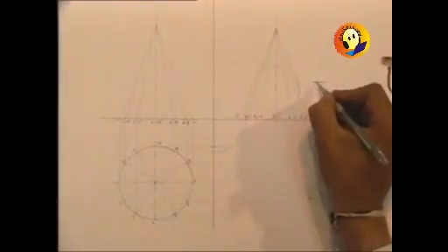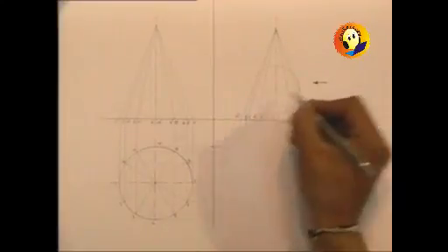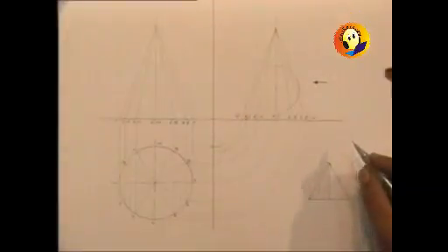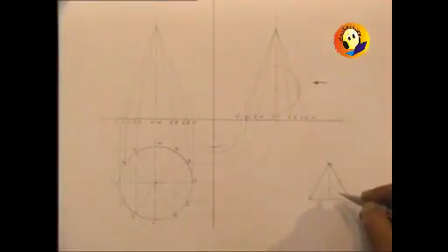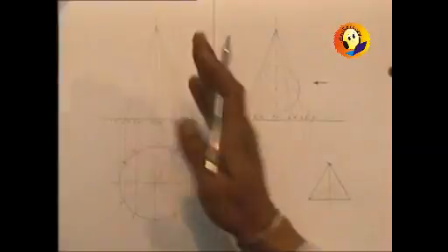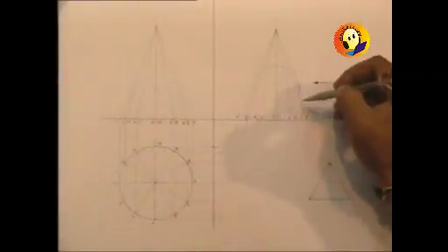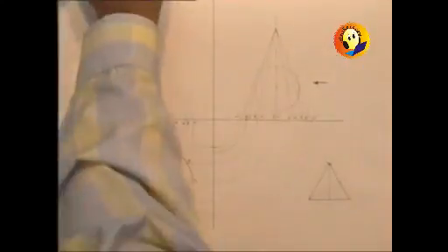Side view will be seen in this direction, so that we can obtain the view called the front view, and it is given that one plane of that triangular prism is parallel to VP. So this is vertical plane in that case, parallel to VP and towards the observer. So it should be like over here. So the vertex goes on the other side.